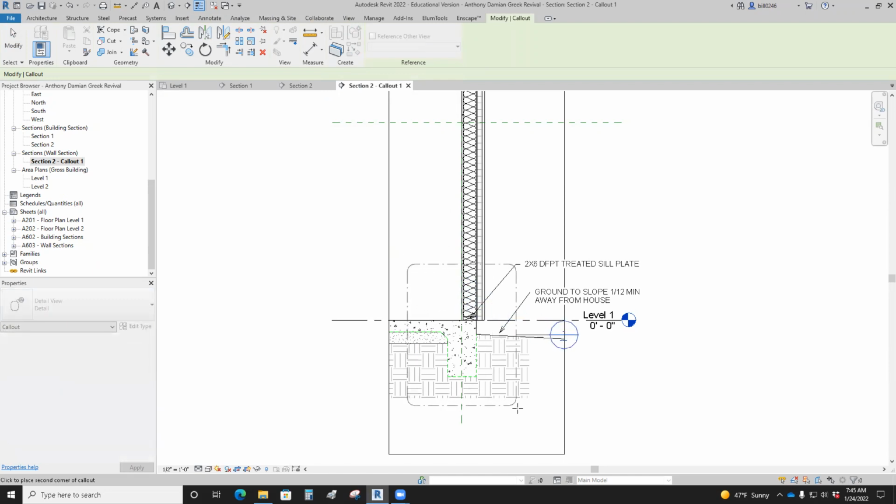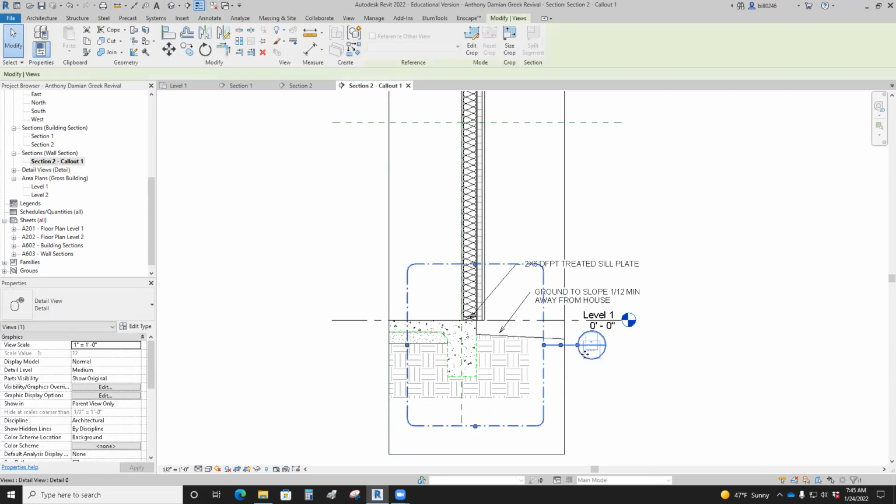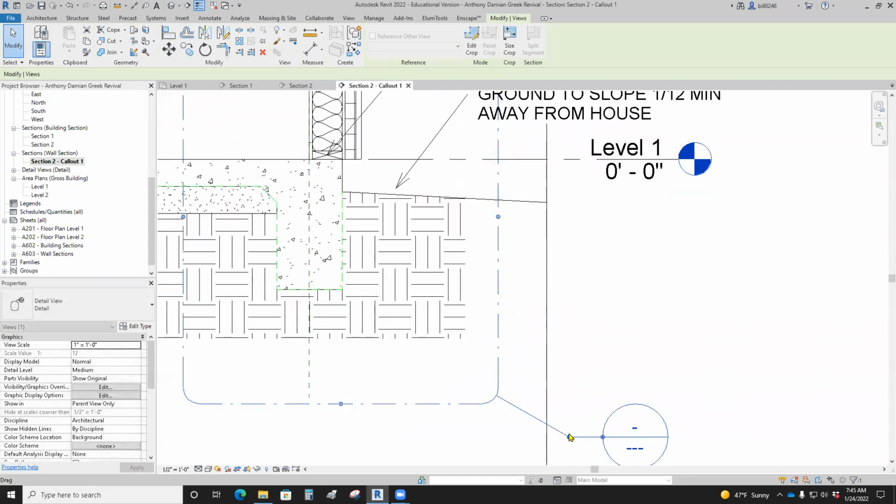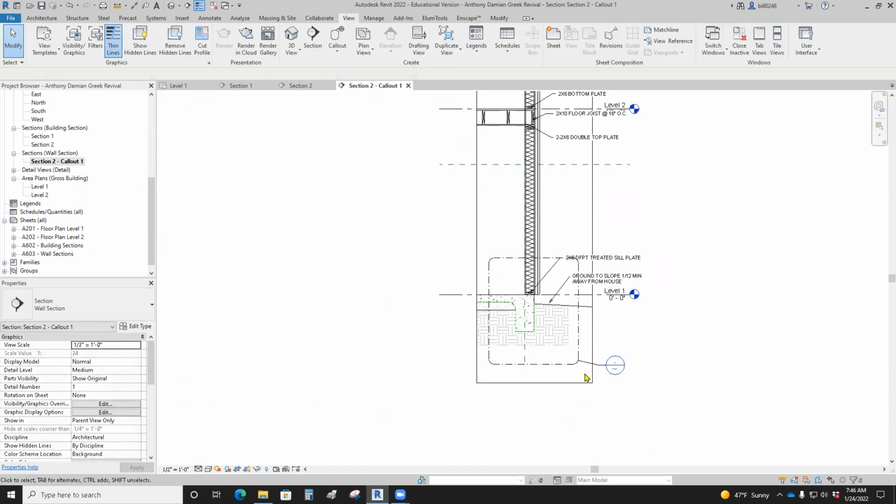We're going to just go right around here somewhere, get that whole bottom where the footing is. I'm going to choo-choo train this around a little bit so it's out of the way. I like doing little elbows like this. They look easy to see. By the way, you can double click on this little guy and it'll straighten it. Little trick. They want the elbows there. They don't want them to look like that. Okay. So you get it like that, get it straight. Now, is it on the sheet yet? Absolutely not. But we now have a detail section.